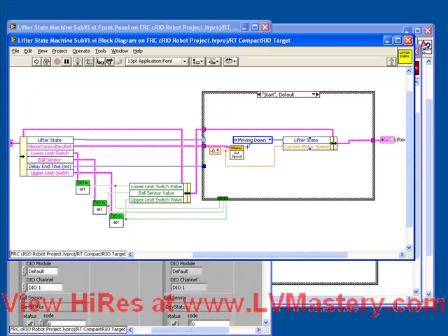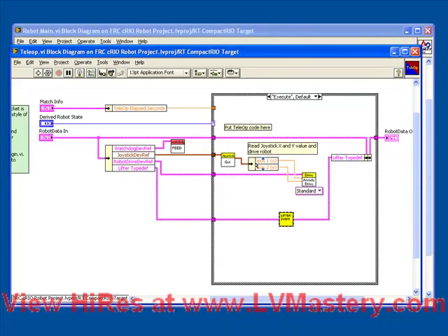We coded that up in some detail in the previous installment, so I'm not going to review this code at all, except to point out one problem. Depending on the nature of this theoretical lifting mechanism, it's possible that that limit switch, either the upper or the lower, is extremely important. It's possible that if the motor doesn't stop immediately on seeing that limit switch, that physical damage can occur. So it's essential that the limit switch be monitored as quickly as possible.